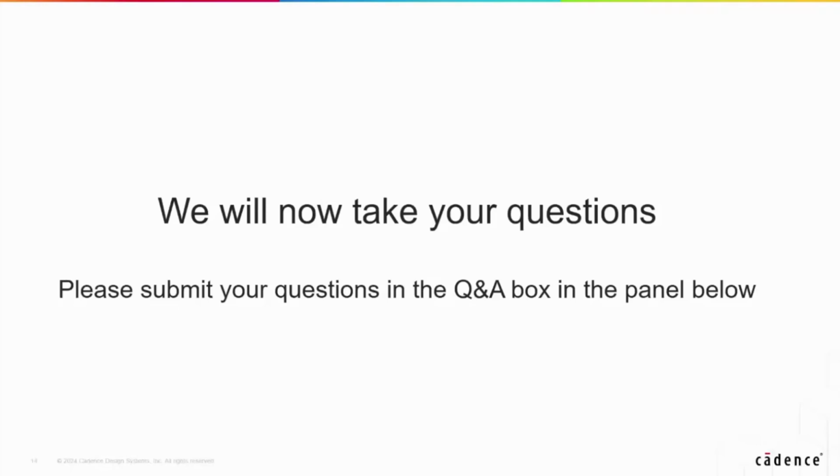Yeah, that's exactly right. So for the questioner, we do make a few assumptions in the InDesign analysis for the purpose of being able to get actionable results back quickly to the designer. But as you get into the sign-off, then depending on whether you're using the hybrid solver or the full wave solver, we can get you very accurate, detailed models for vias, wire bonds, trace parameters, and so on.